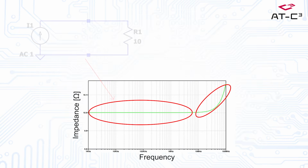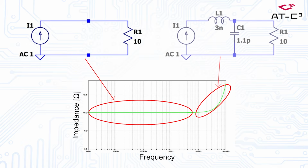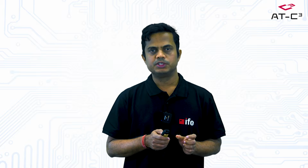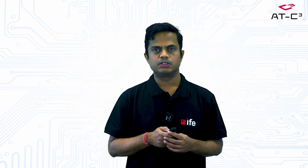At very low frequency, the inductor is a short and the capacitor is open. As you go up in frequency, the frequency dependent behavior comes into the picture. That's why we see a different impedance value. So for our analysis, as long as the impact of the parasitics is low, we can use our network simulation to alter or optimize our design. By understanding this, let's start our filter simulation.